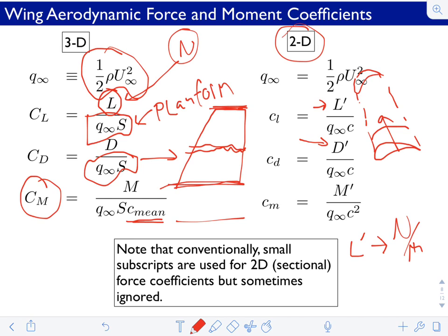We only have to study what's happening in one plane, but an infinitely thin wing in that sense has no lift. It can produce no forces. So we have to consider that we're basically multiplying by one unit in the y direction. And that will give us our force per unit length. So force per meter into the board, into the plane, is what we're doing. That means our denominator will have the same units. So here we do not need an area. There is no area we could have.